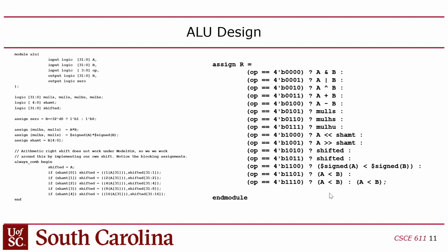Yes? Always begin and always combinational. Oh, right. So always combinational is whenever your intent as a designer is not to have memory, not to have sequential logic. So that's just used as a way to tell the compiler that, right? If you accidentally put a latch in there, it would generate an error. That's all that means. It's the same as saying always at star, except it has that additional check.